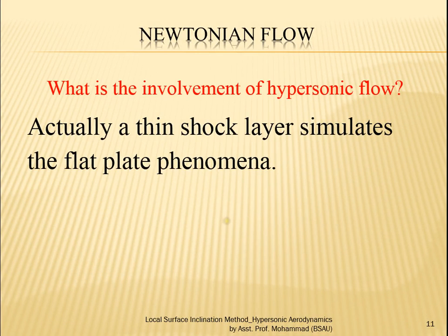Actually, a thin shock layer simulates the flat plate phenomena. This is very, very interesting and very particular to hypersonic flow only. We know that a thin shock layer is actually the hypersonic phenomenon. So in the case of hypersonic flow, the shock layer becomes very thin, and this thin shock layer simulates the flat plate phenomena. Let us see here.